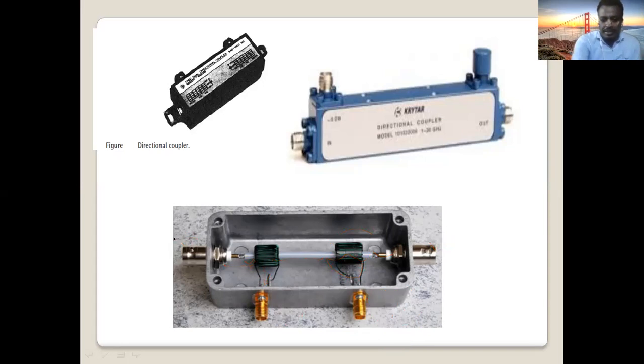Look here, when this is the input, this is our first cable, it is transmitted here. When it reaches here, there is no coupling. P4 must be how much? Must be 0. No division of signal. The signal continues to transmit, but when it reaches here, now it's divided into 2. One will go to the coupled port, one will go to the direct port. A small amount will come here, P3. That is the coupled port. This is the direct port.